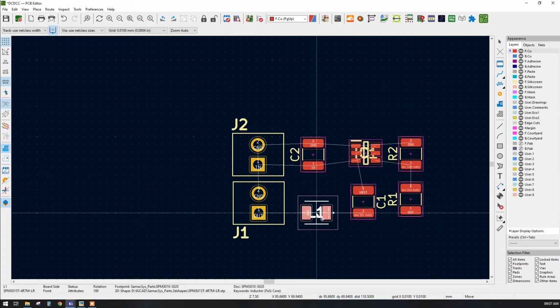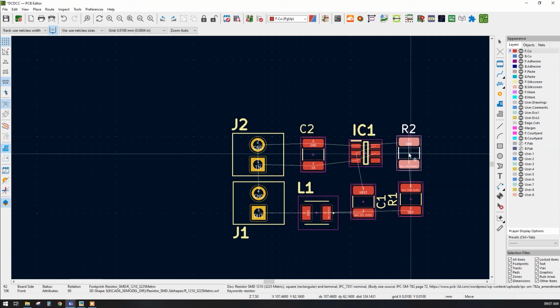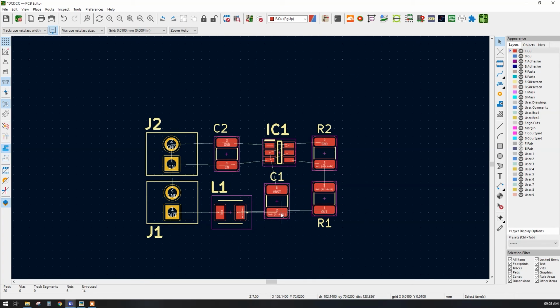Click on this L1, because after routing the components will be moved, so you have to arrange all the silkscreen again, or take care while you are moving it. In this particular case, if there is a movement in the symbol, there will be no issue with disconnection of the nets. So click on this R1, rotate, move, place. Click on the C1, move and place. Okay, so all the component names are proper.